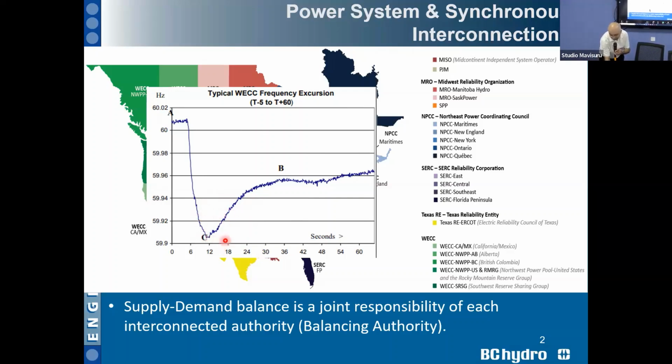I do have an example of different groups, but it's just for educational purposes, not actual purpose. Actually, all the units are on 5% droop. So you'll see that on the frequency drop, all the governors respond within the seconds range, within 6 to 12. So that means within 6 seconds, all the governors have responded to supply the power deficiency by increasing all the units' megawatts, so that the frequency stabilizes at a different set point.